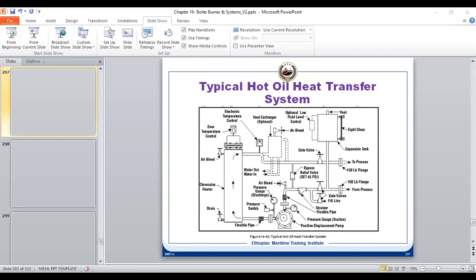If we were to design a thermal oil system, won't we try to put a pump with a higher temperature rating over here, instead of putting a cooler, cooling the oil down and then heating it up again? That means we are burning extra fuel.